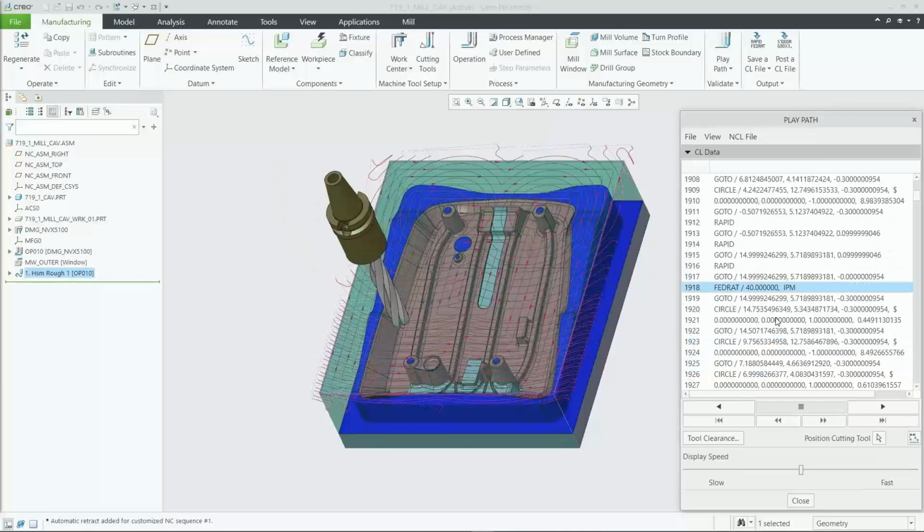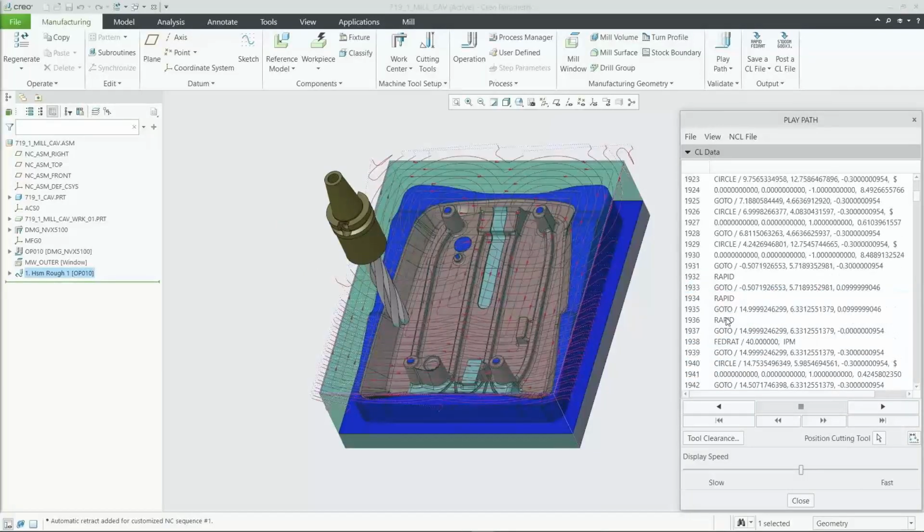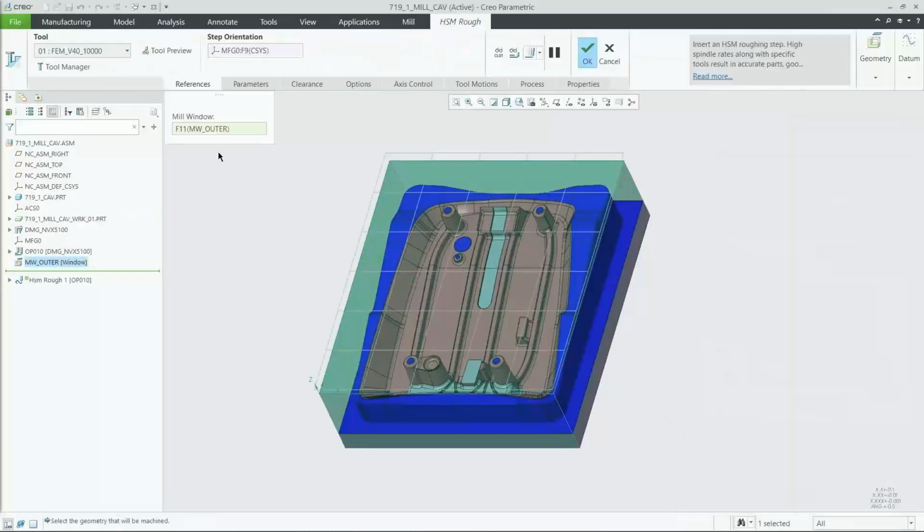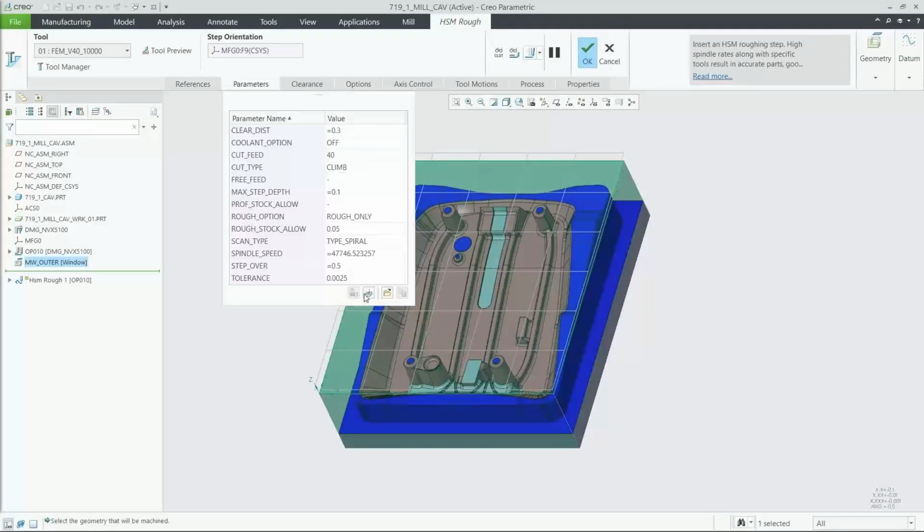It's normally something that's constant and stays the same throughout the process, but depending on the complexity of your part and the different options that you've chosen, that could potentially be a problem. So this was something that was pretty highly requested, something that we've added in now, the ability to do adaptive feed rate control. You can see here within your parameters, all it is an option that you'll first and foremost change here, and then go through and set the different values for your feed rate.